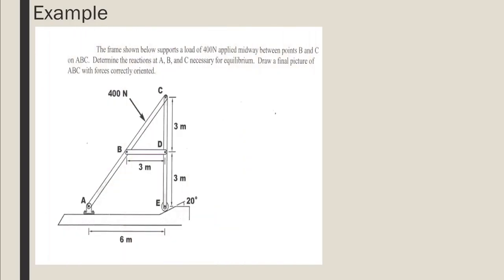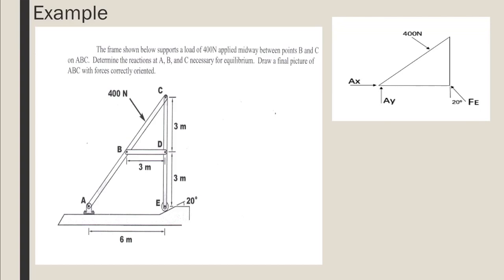First thing we need to do is draw a free body diagram. It's very important to draw a free body diagram to make it simple, and put the reaction forces on it. After that, we can take a moment about point A, because